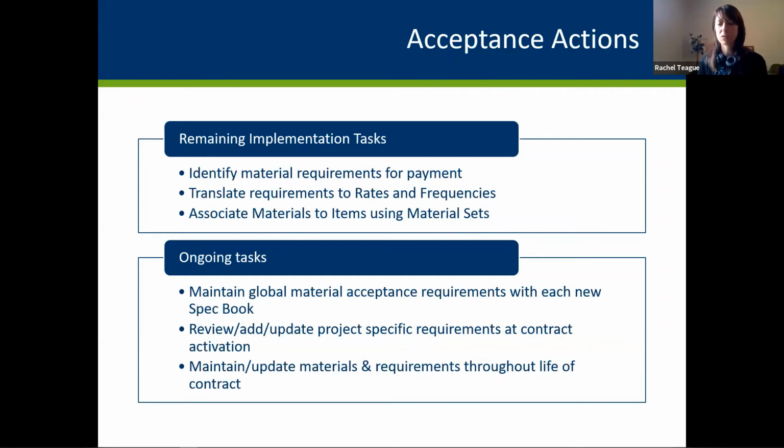So this is also something that we've briefly mentioned previously, but if your item unit is a square yard, but the material is measured in cubic yards or tons or bags or gallons, how do you convert that item unit into the number of material units that go into making 1 unit of that item?